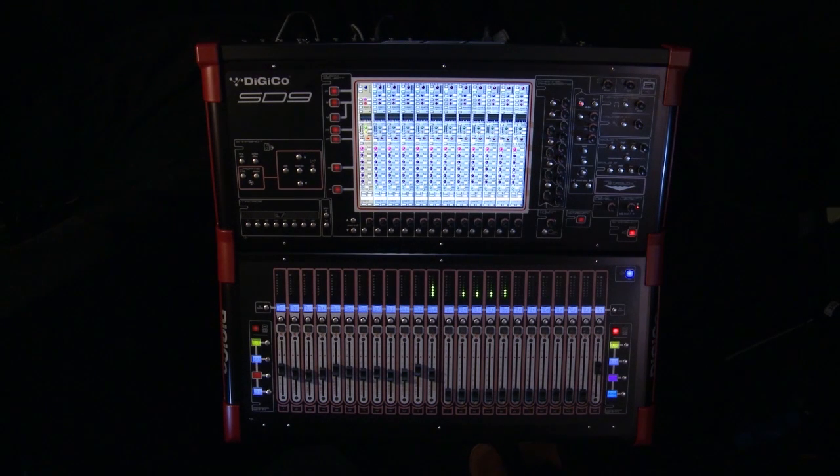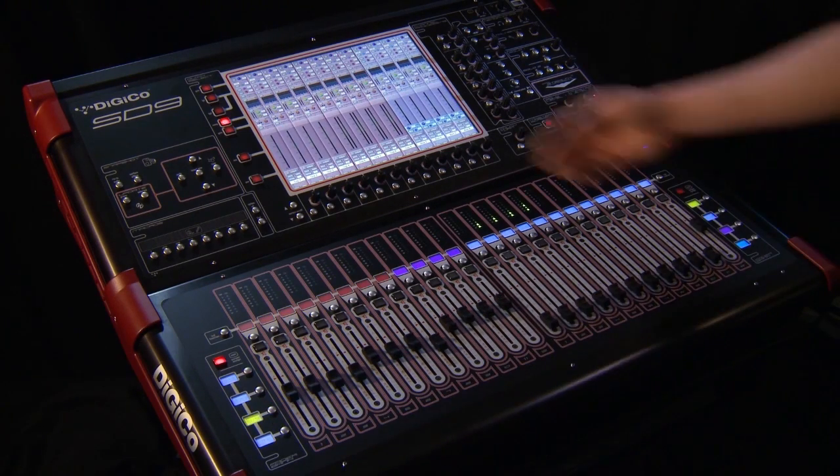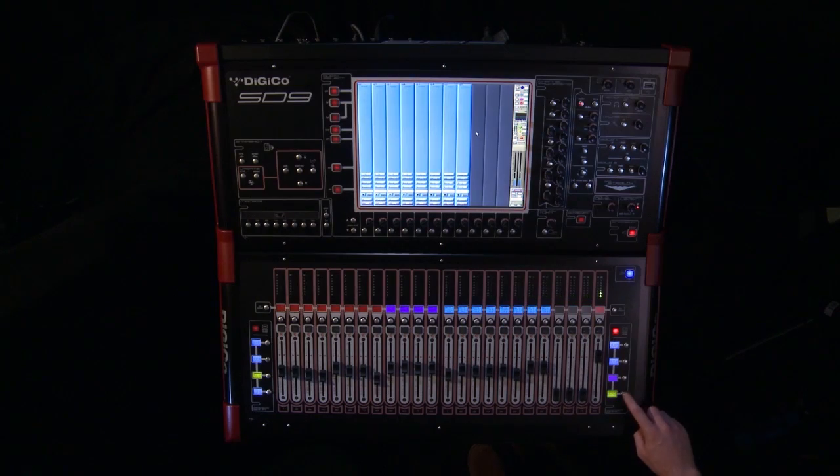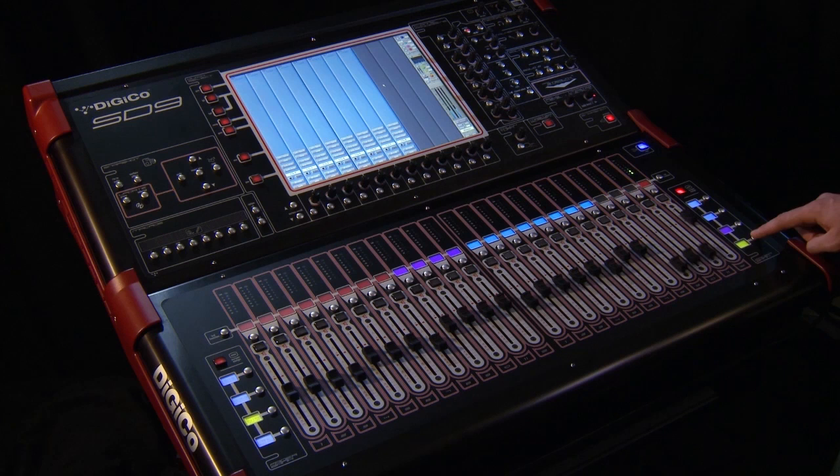Now we have a channel input and output routed, let's look at the different output channels. All the group, aux, master and matrix outputs have the same processing as the input channels. This means, in a lot of cases, no further processing needs to be inserted into the bus output signal path.